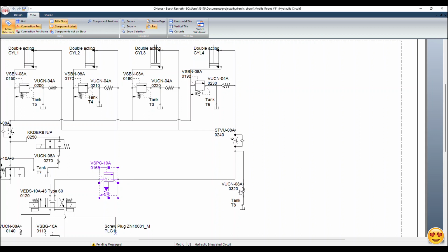This might cause cavitation, and cavitation could happen when you have low pressure that creates a vacuum inside the hydraulic system. Therefore you need extra pressure or extra flow added to the lines, because otherwise it will create a huge pressure gap that might damage the hydraulic mechanical components.